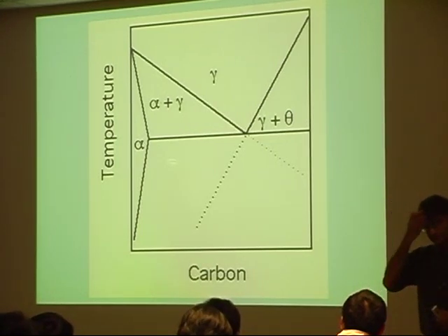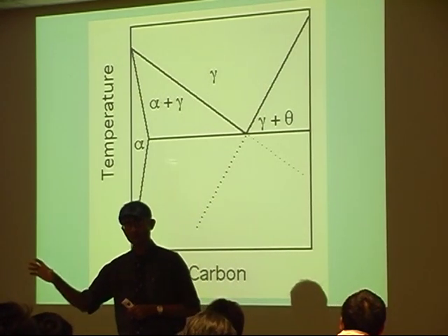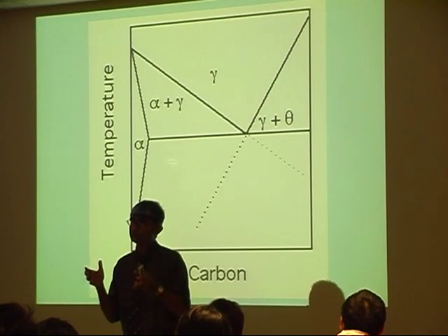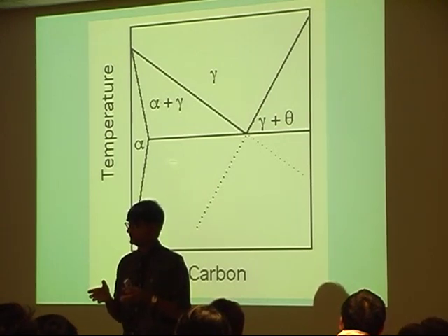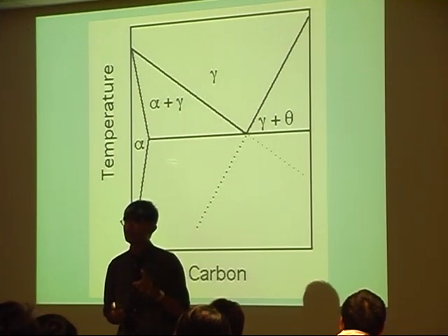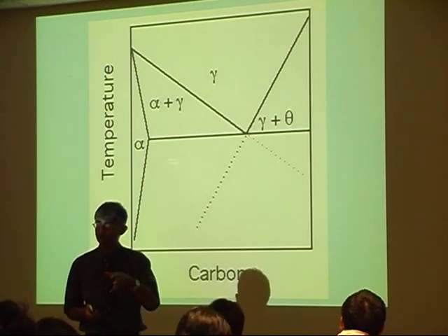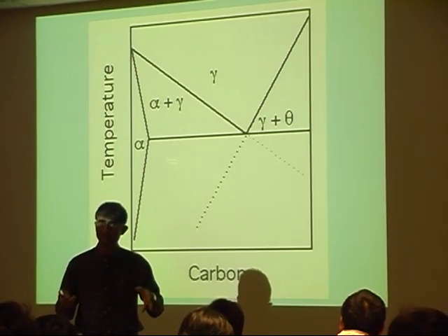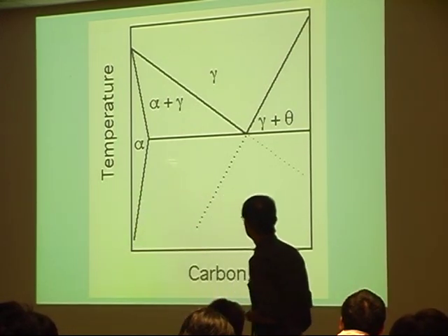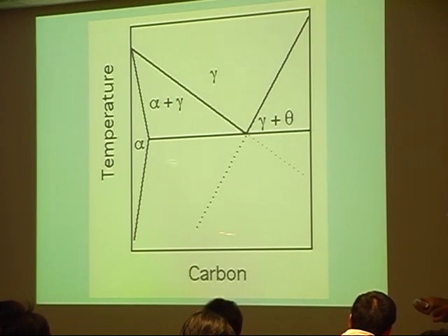Now, one of the problems with all of these methods is that because they use polynomial equations, when we try to do calculations in a region where experimental data don't exist, then you might actually be extrapolating incorrectly. Okay? If you use an empirical equation, then you can't be sure that when you do calculations outside of the domain of experimental data, you will have accurate results. So this is like the iron carbon phase diagram. Very often for bainite and for martensite, we need to do calculations at low temperatures where thermodynamic data may not exist.